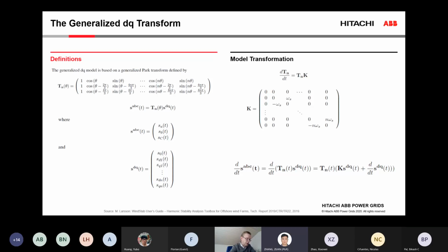So the first point here is that I never derive these expressions for the A matrix by hand. I'm using a special tool called Dymola. That's a simulation tool, you could say it's similar to Simulink, but it has a little bit better support, particularly when it comes to modeling grid components. That allows you then to use automatic differentiation to get these Jacobian elements.